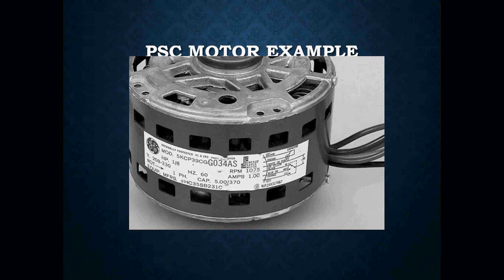What's nice about PSC motors is that usually they have the nameplate stamped right on there, and you can get a lot of information on the type of capacitor the motor uses, which is right here where it says cap. This is a 5 microfarad 370 volt capacitor. So if the capacitor fails for whatever reason, you can reference the nameplate and get a replacement.